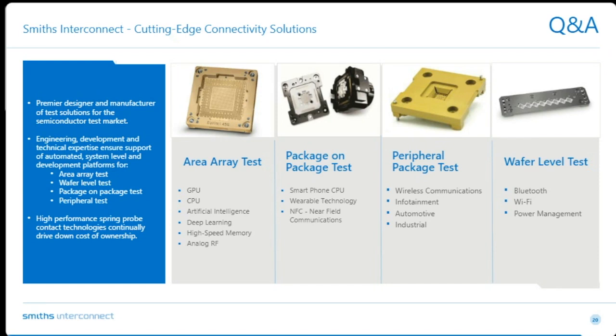One thing that we do have in the Da Vinci portfolio is a couple of different pin lengths, and even with the longer pin, because we can shield the complete signal path and tune the cavity, we still get really good performance even with the longer signal path. That allows for longer stroke and a more rigid socket. So, we're okay up to 90 so far, and I think larger are on their way.